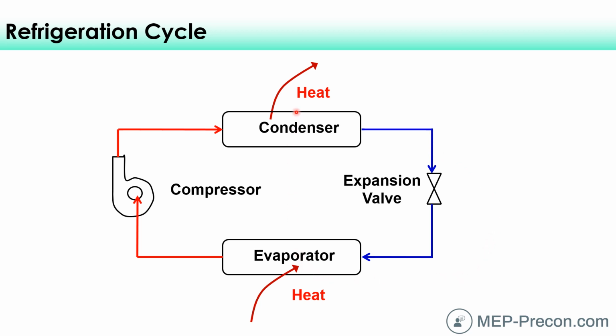So we have two heat transfer devices, an evaporator and a condenser. And let's think of these as air coils. If you're familiar with an air coil, it's kind of like the radiator of your car, if you've ever seen that. If not, open up the hood and take a look at it. It's in the very front, but water flows through the small tubes that you can see in the radiator, and on the outside of those tubes, solidly connected to those tubes, are some fins. So there's some heat transfer that takes place between the water and the air within that radiator.